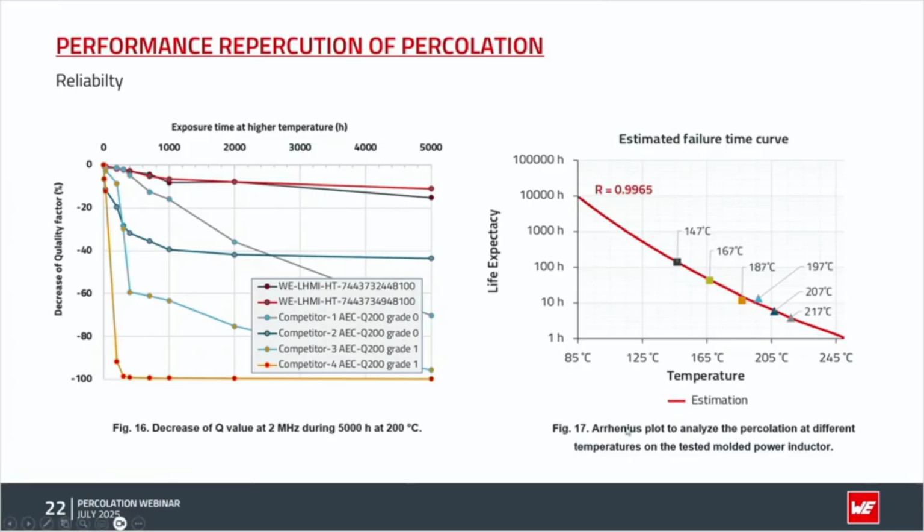These kinds of curves, Arrhenius plot curves, allow us to show you that if you choose the wrong part, you are not safe if you work at lower temperatures. You can have the effect. So it's not that if you offer a part that can work until 150 degrees, you are safe if you work in this area. No. It can be as well that you don't suffer from that if you offer a solution that runs 1 hour per day, 3-4 days per week.